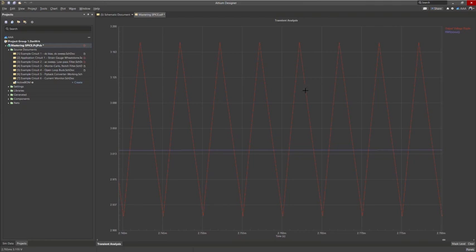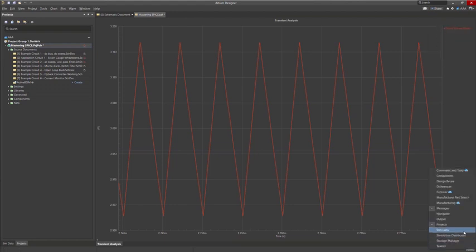So my RMS value is supposed to be 3, which is what it's at. We'll just say this is 3. So that is fine, but my boss told me that my voltage ripple needs to be at 1% or less. So let's test where we're at, and let's actually bring up the simulation dashboard.